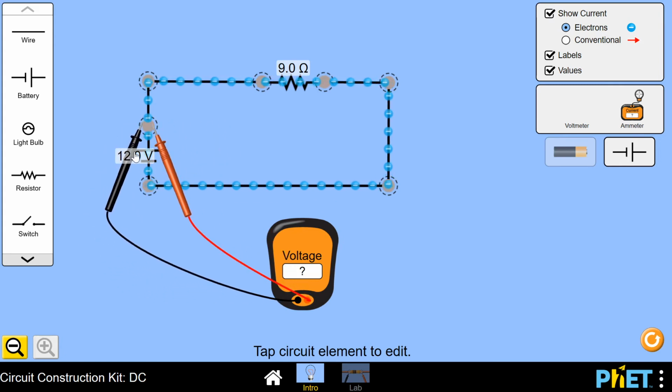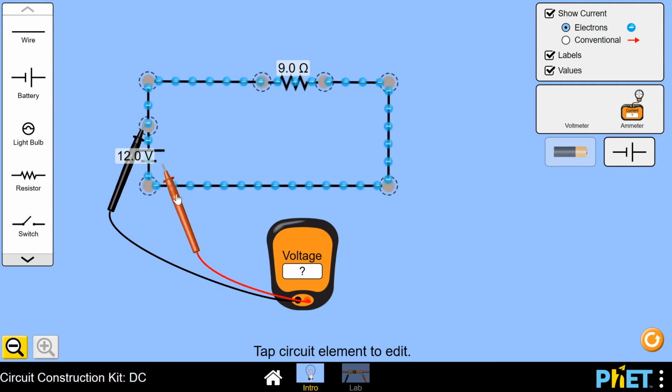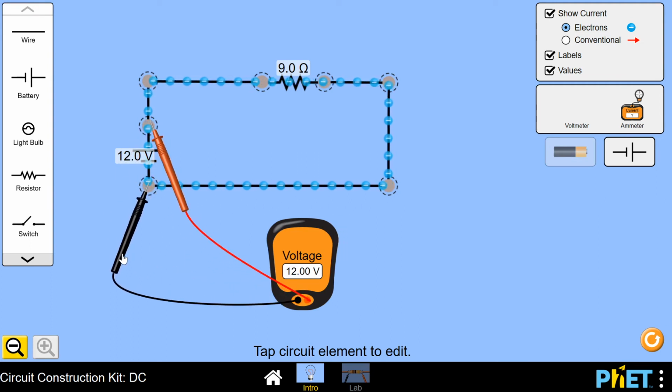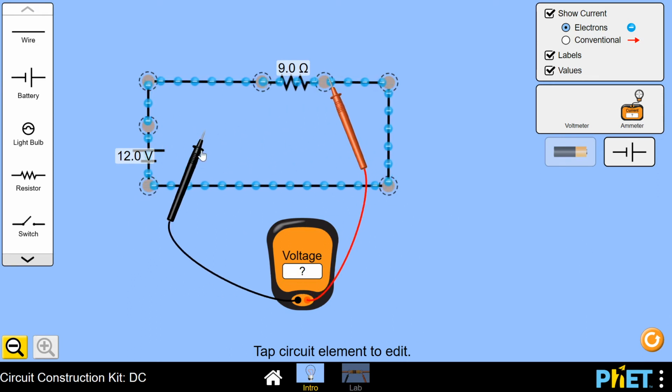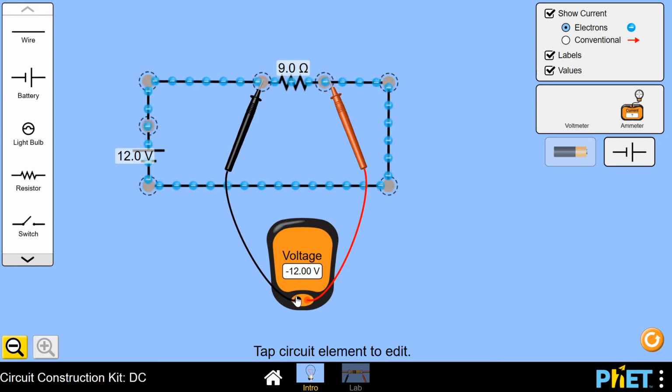And it depends on which side. The polarity is important. If I put the probe on the wrong side, I'll get the negative reading. So in most cases, I want you to just look at the numbers. Don't worry so much because you're not good enough with this yet to understand what that negative and positive means. That's fine. If you put the two probes across, say, for example, a component like a resistor, if it's a positive or a negative, you know that the resistor is causing a drop that is equal to whatever this reads out. This is a unique case. I'm telling you, in the future, you're not going to see that this voltage drop, if you have multiple components, is going to be exactly the same as the battery. There's some other things that might also occur.